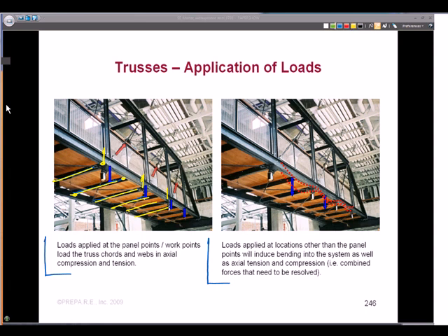Well, I bet it has to do with this wood flooring. It can probably only span 6 feet. It can't span 12 feet. So if you have a 100-pound per square foot live load on this system, and there are people walking up here, then there needs to be an intermediate beam so that the wood will work out. But the truss only needs its bays at about every 12 feet on center. So they've put in an intermediate beam.